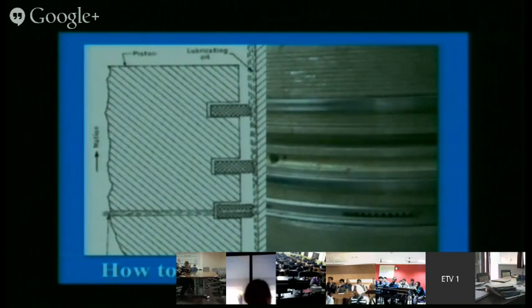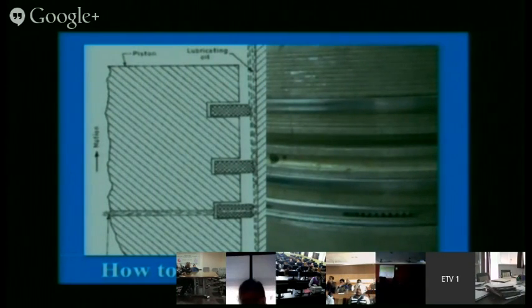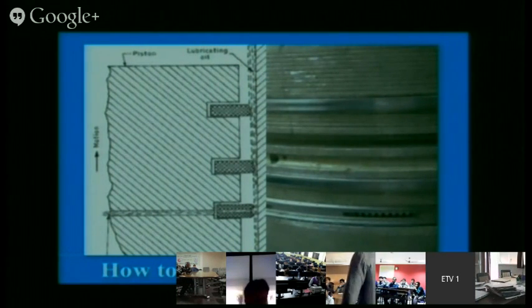The reason is that lubricant from the downside is going to the upside, so it may pass to the combustion chamber if a proper design of the interface is not there. So both ways it is crucial. If exhaust gases are passing through the interface, then also it is problematic and efficiency will go down. And if lubricant is going up, then also it is problematic. It is not economical. So the design of the interface should be proper.